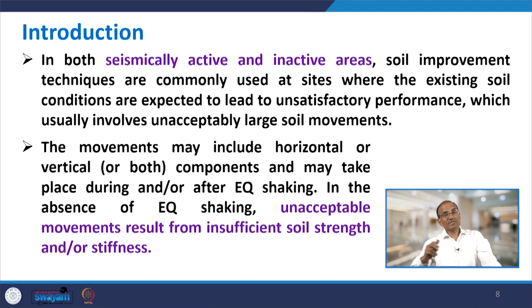When you go for foundation design of the structures, there are two most important criteria which need to be satisfied for any foundation. One is that its bearing capacity should be within permissible limits. Whatever the soil, the pressure the structure applies at the base should not exceed the safe bearing capacity of the soil. So, that is the bearing capacity criterion. The second important issue is that the settlements or lateral movement of the soil should be within the permissible limit.